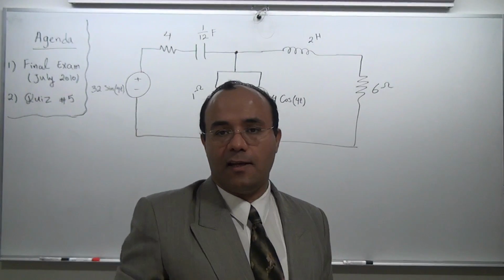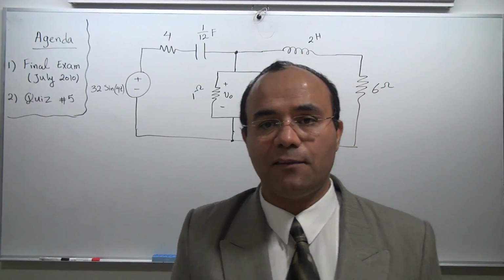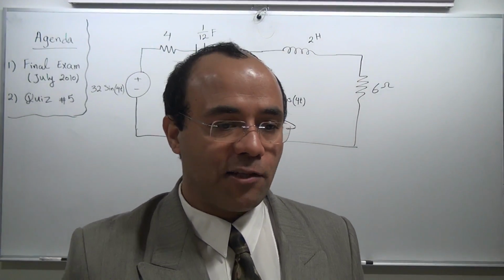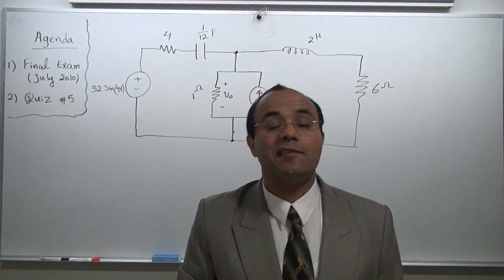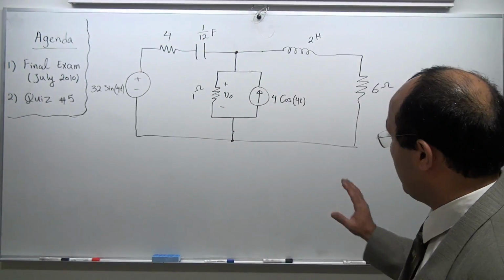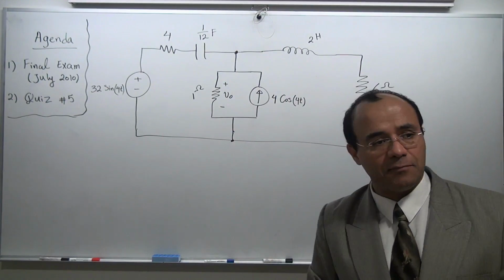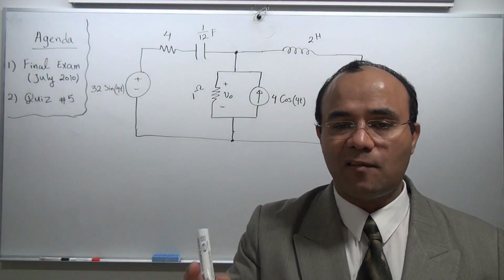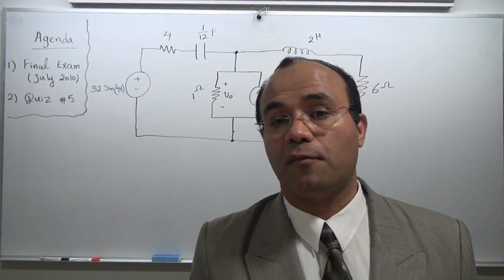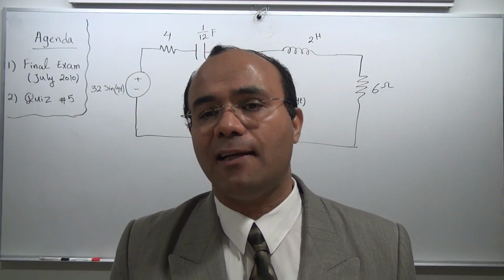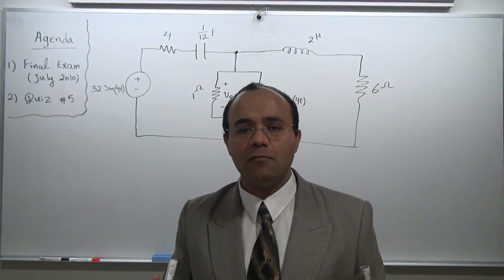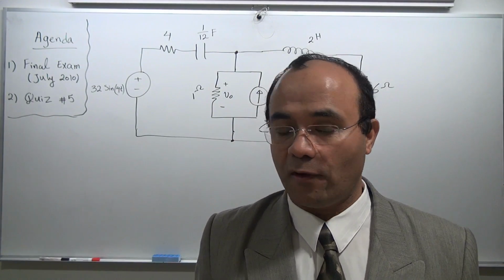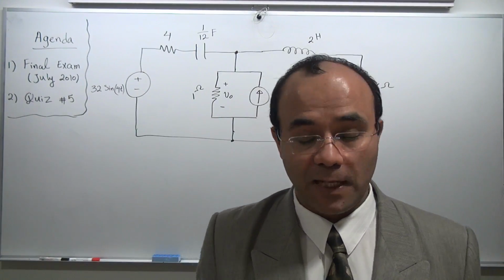Of course you can solve this using differential equations, second degree differential equations, and even present to us the transient response. But in chapter 10, all we care about is the steady state response of this design. We had an algorithm discussed last time, and the algorithm says, take the design, piece by piece, element by element, into the frequency domain. Then you are going to have this entirely in frequency domain. The benefit of that domain is even a capacitor then behaves like a simple resistor. It's going to be a complex resistor in one sense.